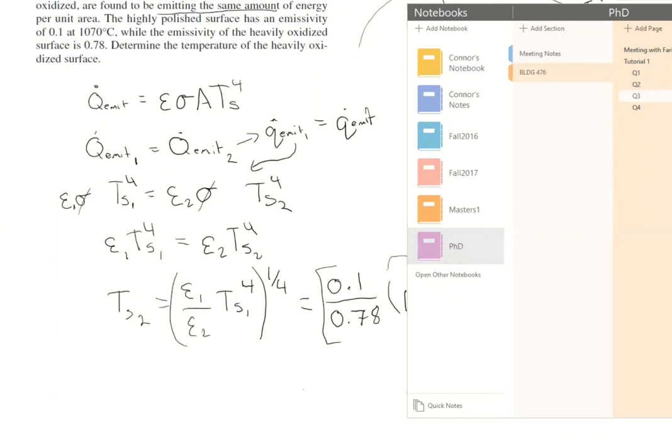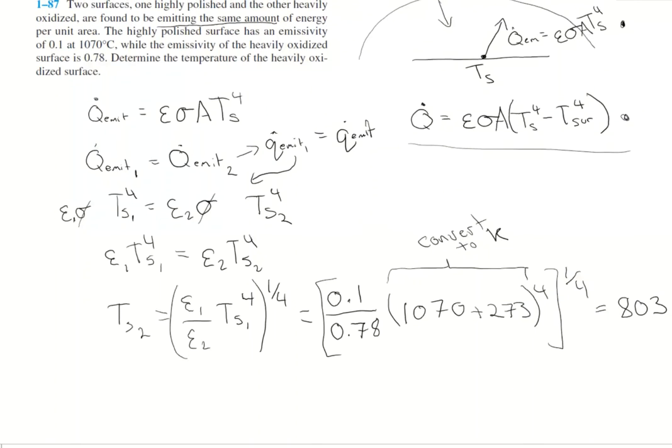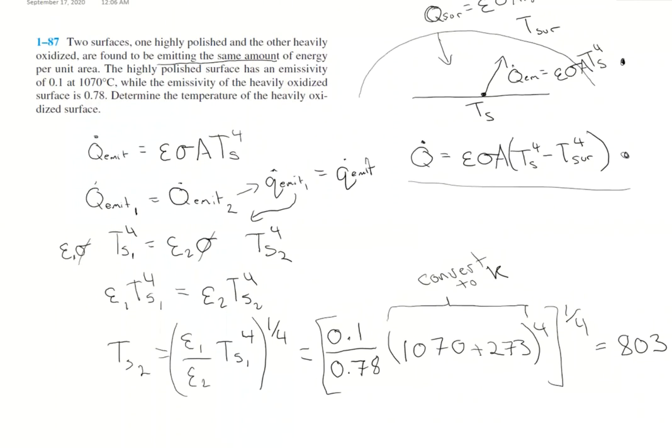Oh, so I guess, again, just to bring this back to buildings. Radiation actually has a pretty big role to play in buildings. I'm sure you guys have seen that already. Normally radiation is a very small number multiplied by these temperatures that are to the 4. If there's a really big difference, then this number can get really large. But if this difference is small, this number is pretty small, and so the effective radiation is pretty small.